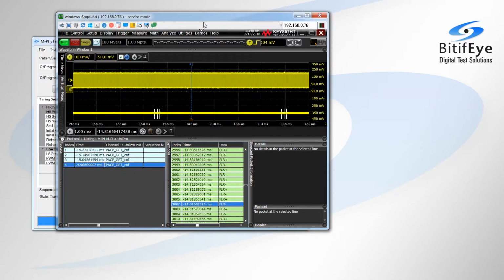Now the instructions need to be sent to the DUT to come out of Hibernate. After that, the number of lanes is set and the transmitter and receiver gear must be configured. So different kinds of registers can also be set in the sequence file, which is sent to the DUT.